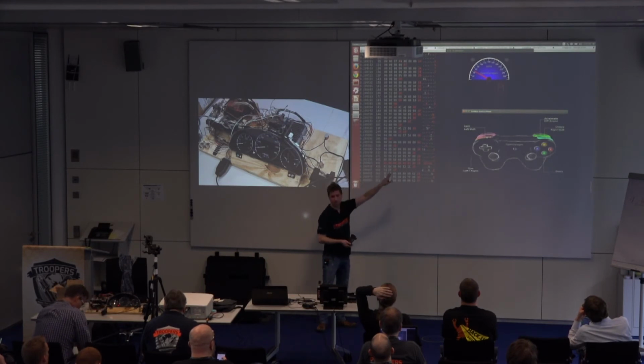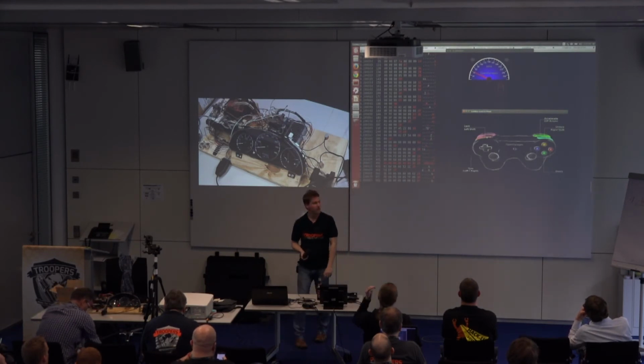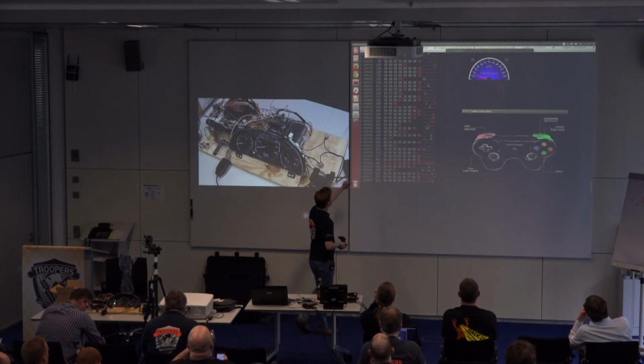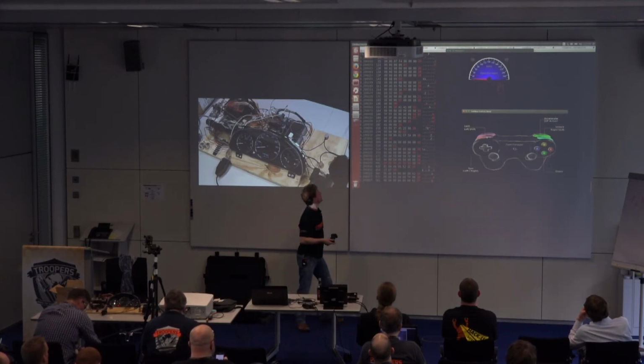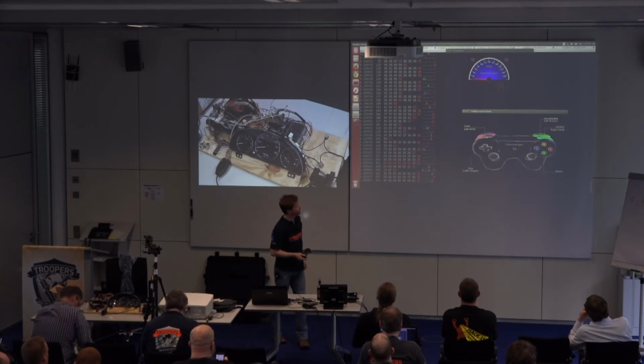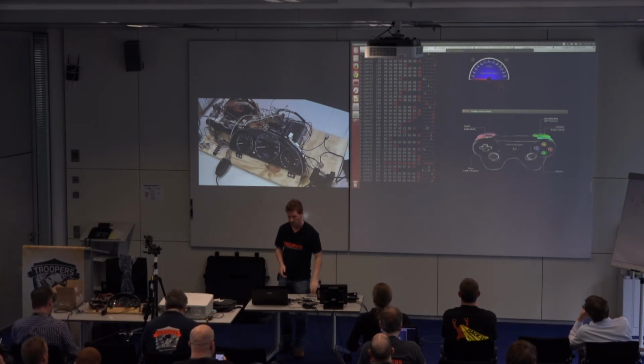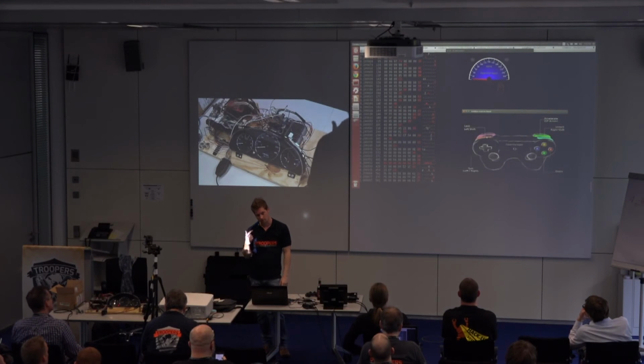do is you'd broadcast those 2 with a higher number there. And you want to go faster than the actual cycle counter. So if a 244 is going right there, so is it like a 0.2 milliseconds? So you just want to go faster than 0.2 milliseconds. Or if you're crafty, you'll look for that particular signal and immediately send afterwards. That will prevent from flooding the bus.